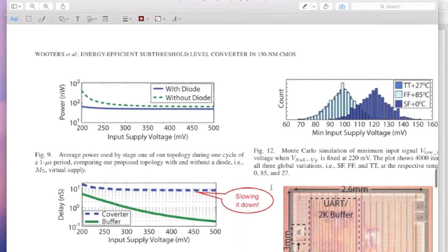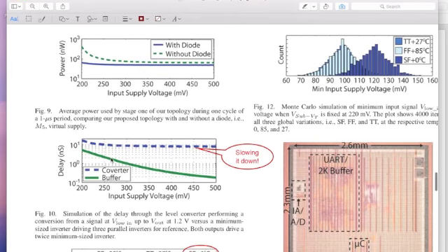Now one thing is, having done the design, they characterize the power and the delay across different input supply voltages. So here, for example, what they are comparing is that as supply voltage reduces, the buffer, which is just a simple inverter, its delay goes up, which is what we expect. Remember, on this side it's a log plot. Okay, the delay of the level converter is really substantially reduced, whereas the delay of the buffer doesn't change much in the log plot.